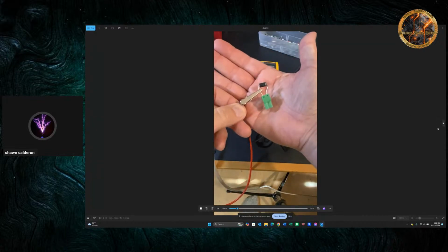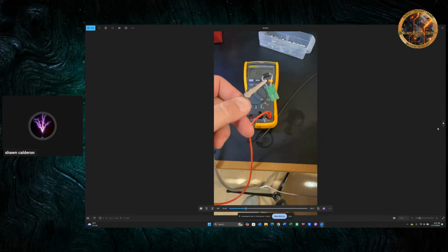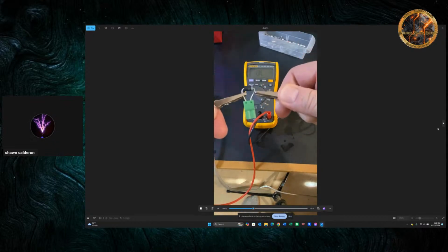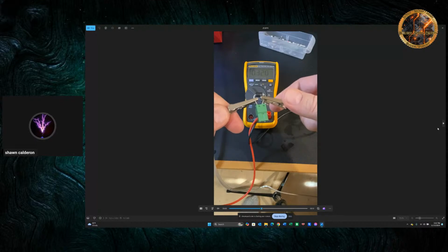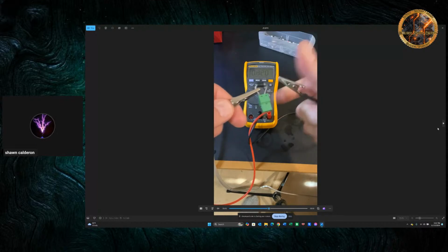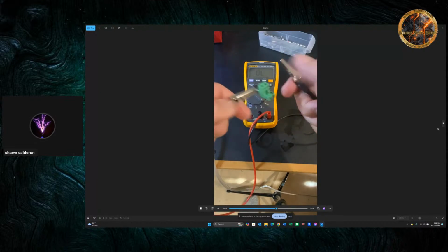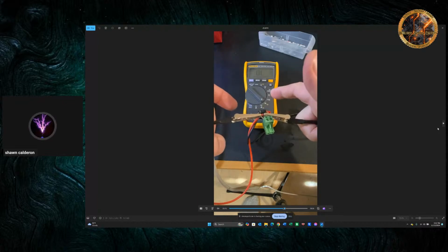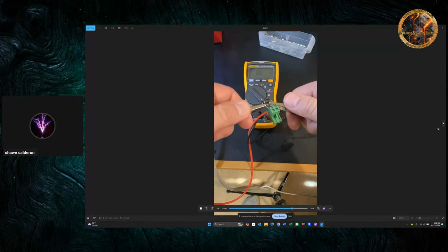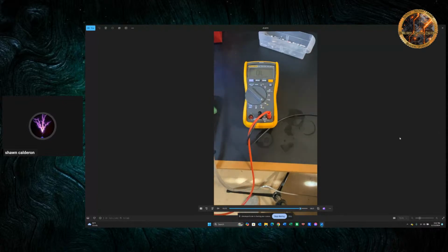And as we tested the other input diodes, we're going to test this diode. This is a Schottky diode, but it works just like others. 0.3 volts one way, 0.32 there. The other way, it's an OL. There you go. The difference between Schottky diodes and regular diodes is Schottky diodes are really good at handling high frequency, and they can also handle a whole bunch of current. In fact, the Schottky that I had there can handle 500 amps of current. Yeah, 500 amps. It's pretty crazy, but that's the Schottky diode.